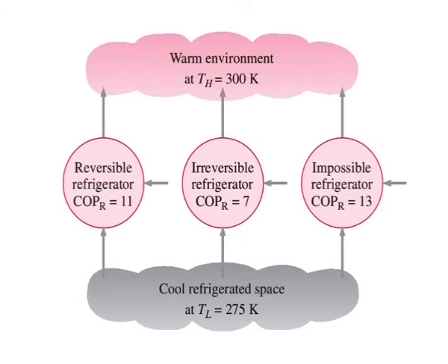The COP of a reversible refrigerator or heat pump is the maximum theoretical value for the specified temperature limits. Actual refrigerators or heat pumps may approach these values as their designs are improved, but they can never reach them. As a final note, the COPs of both the refrigerators and the heat pumps decrease as TL decreases. That is, it requires more work to absorb heat from lower temperature media.